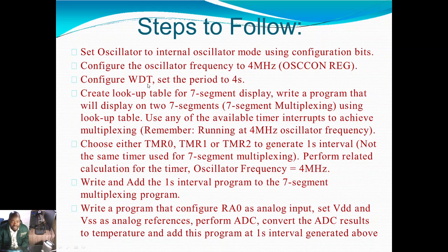Now, the next thing to do is the watchdog timer. What is the watchdog timer? The watchdog timer is an internal timer in the microcontroller that will increment automatically as your program runs. It will increment, and if it reaches a predetermined time without being reset, without clearing it, it will cause your microcontroller to reset. In this case, we need to configure the watchdog timer so that it can reset the PIC in 4 seconds if we don't clear it within 4 seconds.